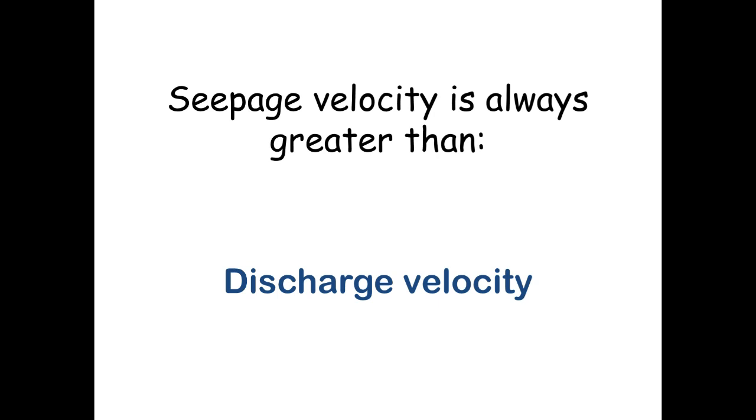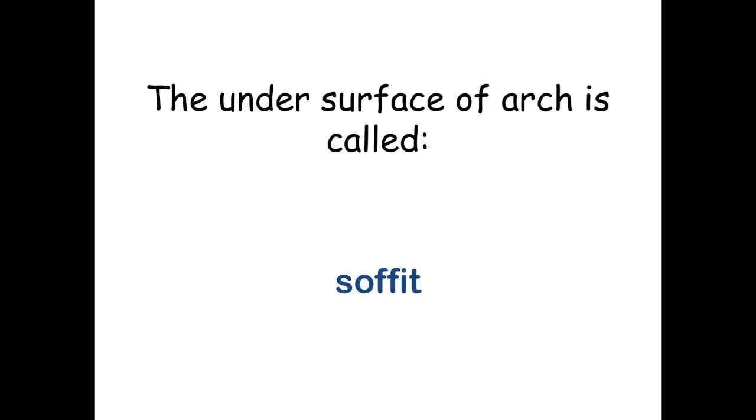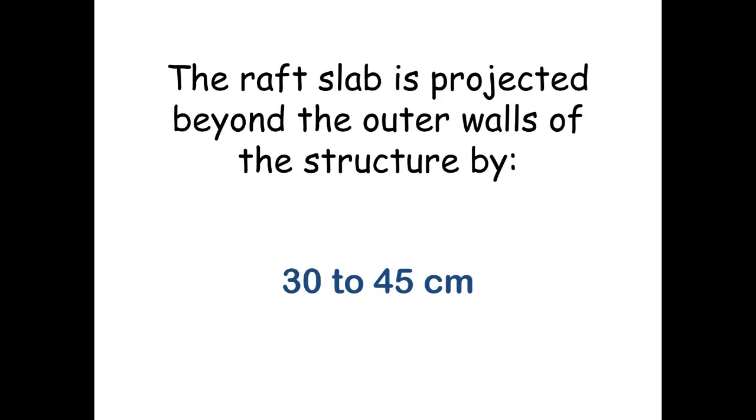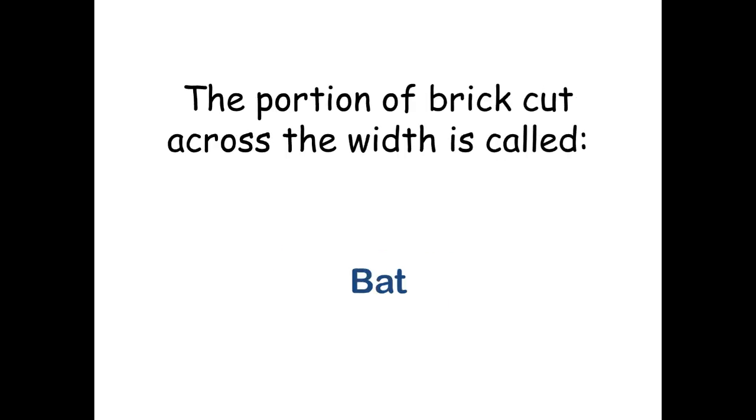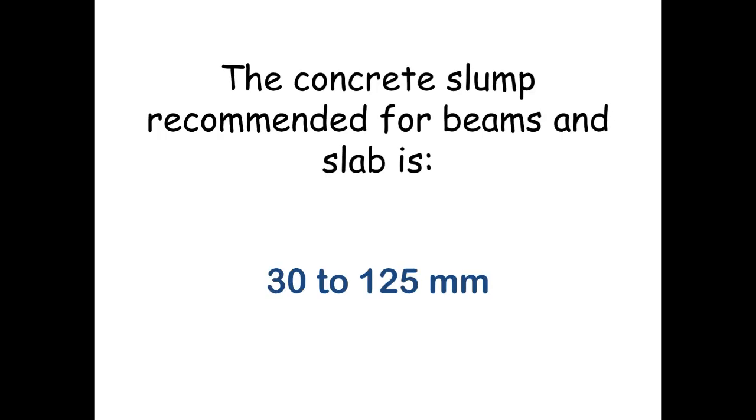Seepage velocity is always greater than discharge velocity. Unconfined compression test is only suitable for clay soil. The undersurface of arch is called soffit. The raft slab is projected beyond the outer walls of the structure by 30 to 45 cm. The portion of brick cut across the width is called batt.